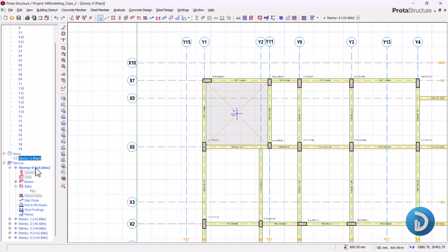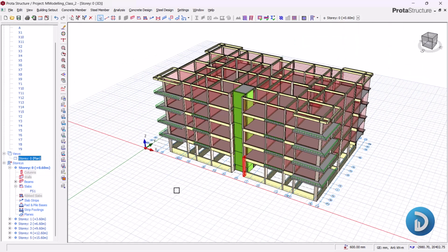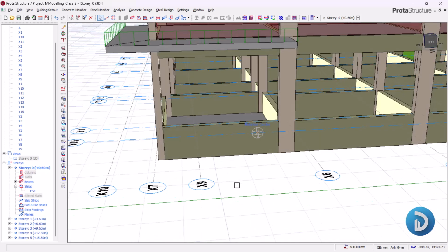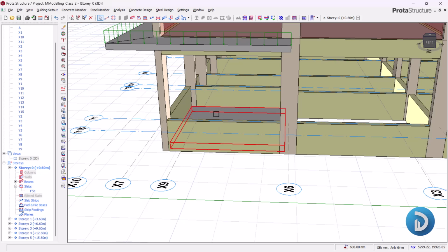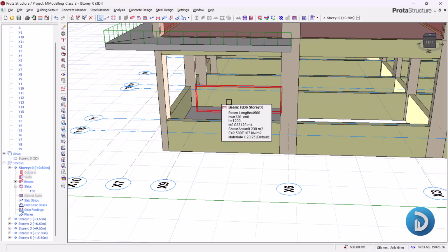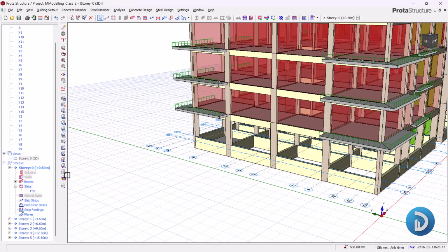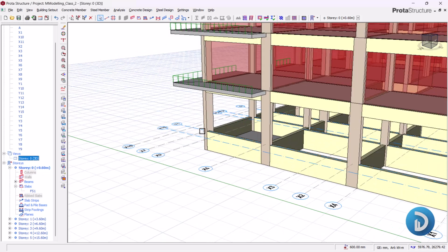So if we come to our 3D view, you will observe that this slab that we've inserted on our beams is actually at the bottom of our beams. But we need to take this slab up to flush with the top level of these beams, except you are designing for an upstand beam, or using the upstand beam system of beam raft foundation. But for this raft foundation, we are using a downstand beam, so the beam will have direct contact with the soil and not the slab.